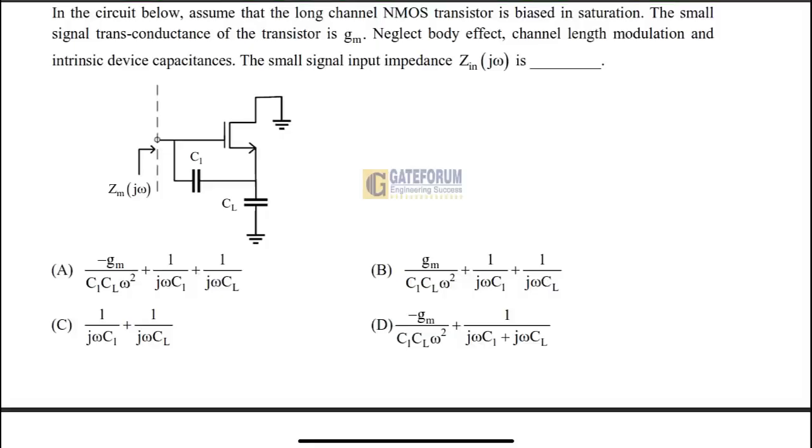So the statement of the question here is: in the circuit below, assume that the long channel NMOS transistor is biased in saturation. The small signal transconductance of the transistor is gm. Neglect body effect, channel length modulation and intrinsic device capacitances. The small signal input impedance Z in terms of j omega is...